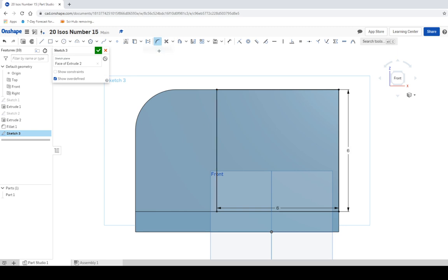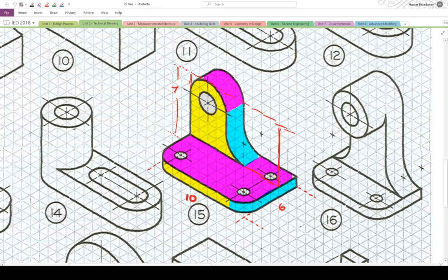When you click on this button and it's highlighted blue, you can click on two edges of a shape and it will create a fillet. Notice that the radius says 0.25. We want to make that a lot bigger. The radius is going to be a radius of 2. So if we click on that R for radius, and double click it, and change that to a 2, you should get a fillet that moves in a nice sweeping motion across. If we look back over here, that fillet has a radius of 2 going out like this. So when we cut it, it's going to just leave this spot behind, and it's going to take away everything else.